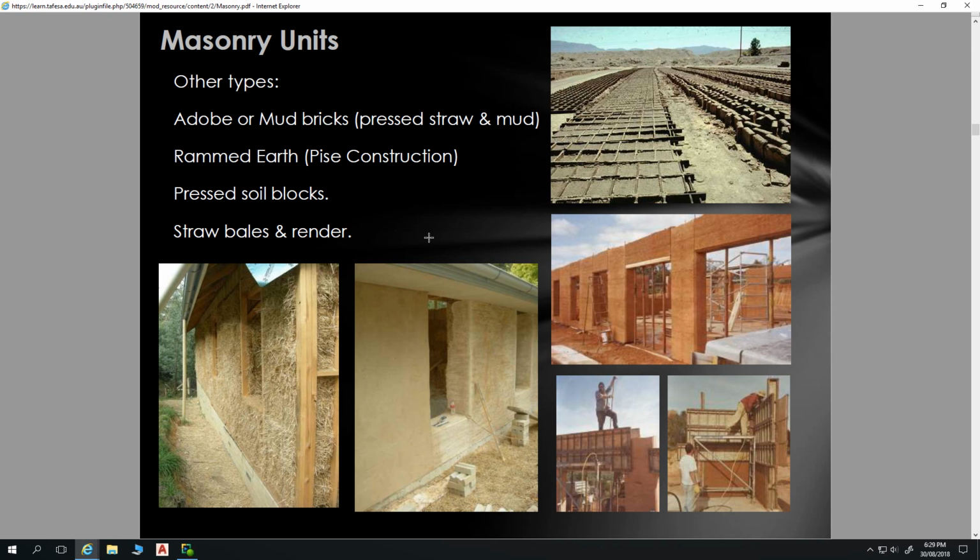What that fellow was talking about on Monday, in the section I missed, I got told by somebody else, is that they've now developed a way of doing rammed earth with a layer of insulation part-way through the wall. But exactly how that's done, I don't know. I'd be interested to see how that could be done. Apart from that, if you're using it as an external wall to meet the R value requirements of the National Construction Code for Climate Zone 5, where you have to have R2.5 in your walls, you've got to do an external stud wall and then insulation, and then you clad it with something else on the outside.